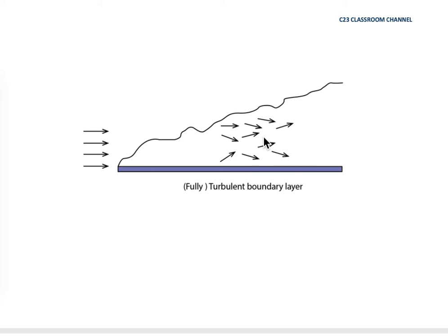I hope you could imagine turbulent boundary layers. Let's say we have one flat plate like this, and we have a free stream velocity here flowing from left to right. When it hits the plate, the no-slip condition occurs, and it creates resistance, and it creates boundary layers. However, the velocity here is chaotic, and it creates a turbulent flow inside the boundary layers, and we assume that the boundary layers can be drawn a little bit rough like this. So bear in mind that in this calculation, we assume that all the boundary layer here is in turbulent flow.